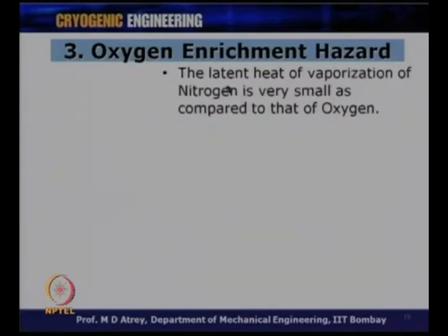This is a possibility. Now, when the air is condensed or solidified, the latent heat of vaporization of nitrogen is very, very small as compared to that of oxygen. So, air is nothing but, let us say, nitrogen plus oxygen. So, the latent heat of vaporization of nitrogen is very small as compared to that of oxygen, and therefore, nitrogen will get evaporated from there.